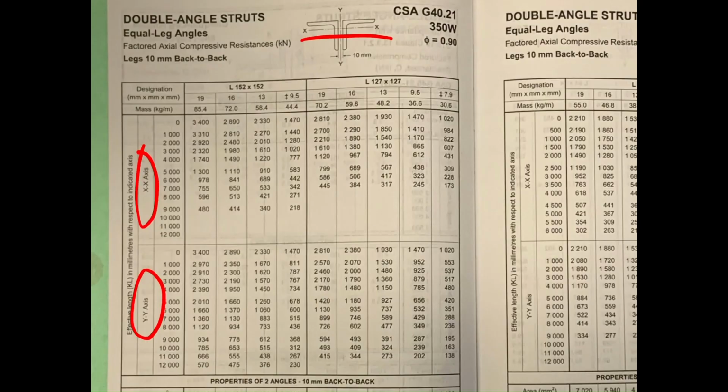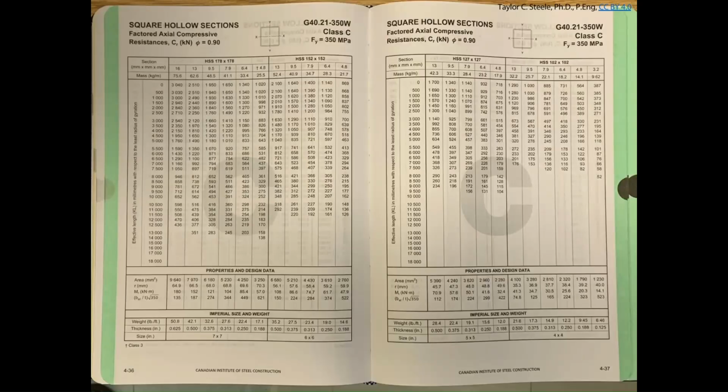Most of them are for wide flange sections, and we're going to focus on that shortly. When we have wide flange section tables, we can do it for strong or weak axis buckling based on the Rx over Ry ratio. Some of them are for HSS. It's pretty much the same thing, except you need to be careful about the class. You'll have watermarked values for C or H or A500 to help make sure that you're picking from the right tables.